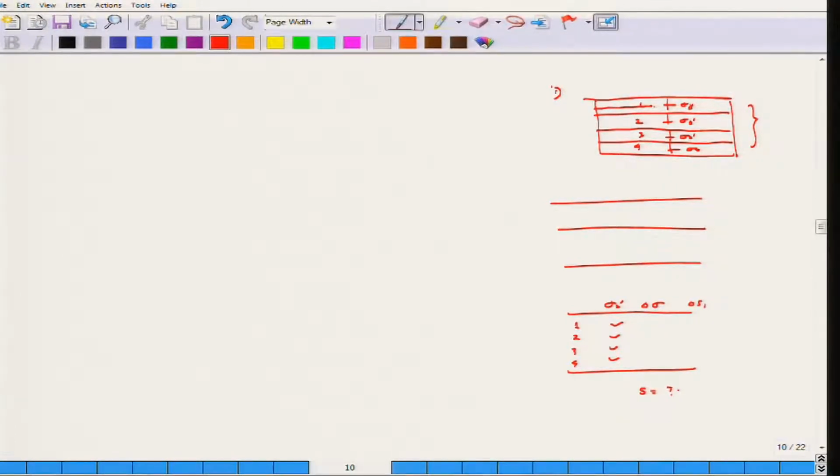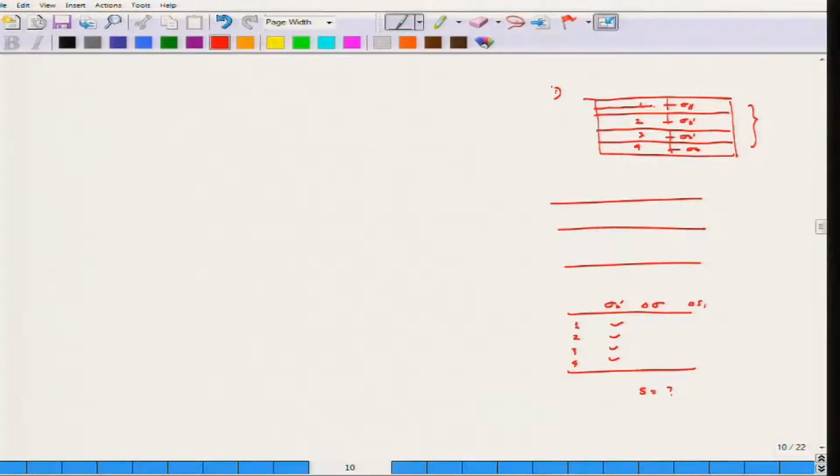This is a very important fact, you must remember this: if the clay layer has a greater depth, you have to divide it into a number of subsections. It may be 2, it may be 4, whatever is appropriate, but generally you should divide it into as many small sections as possible, so that the settlement becomes closer to the settlement observed in the field. In this case, since the clay layer height is small, 4 meter, we find the stress at mid depth or mid height of the clay layer.